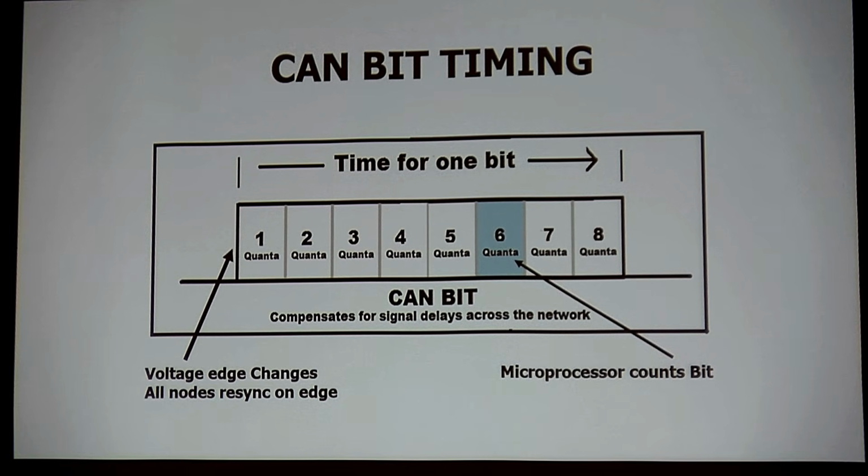So in order for that to happen, we do not sync on an edge, the first edge. There is 2 types of synchronization, hard synchronization and soft. Hard is where as soon as we start frame, everybody starts a clock and they're all trying to keep time to that clock. That's hard. Soft is every edge that I have in the message is trying to keep synchronization. That's soft synchronization.